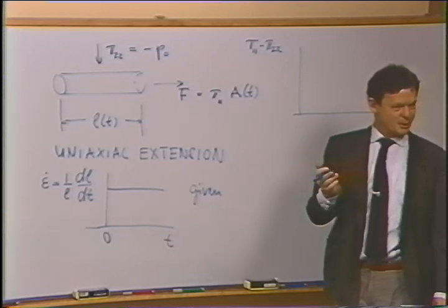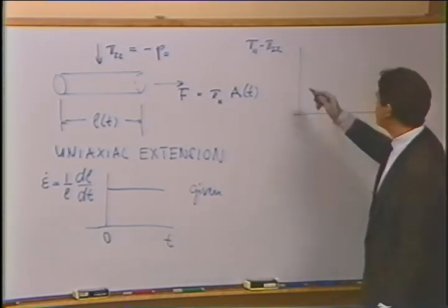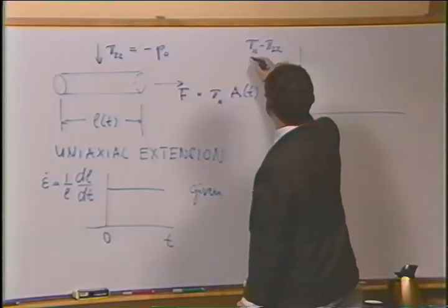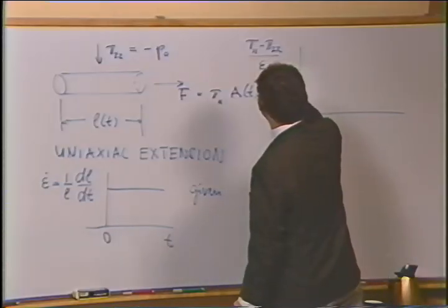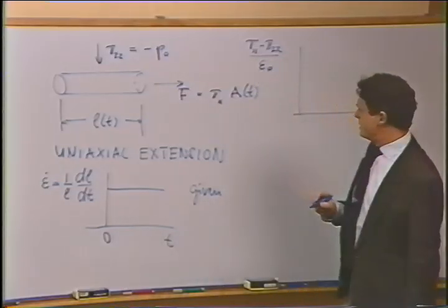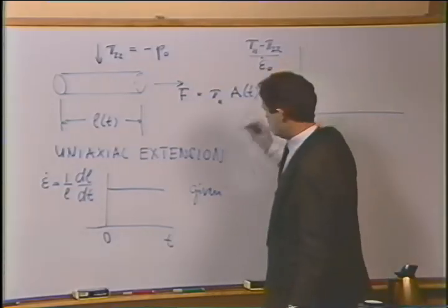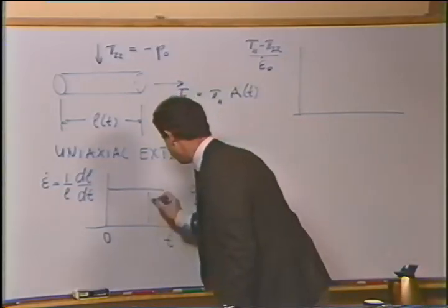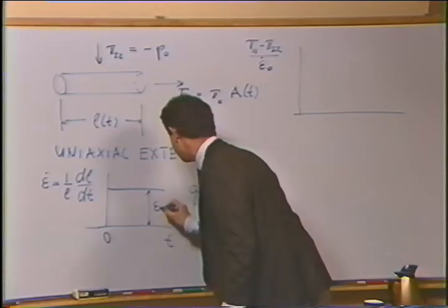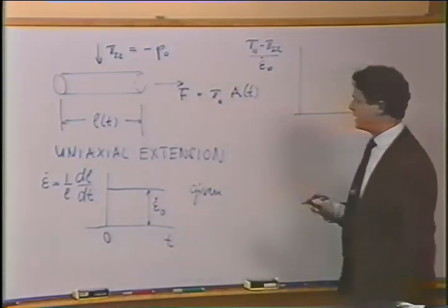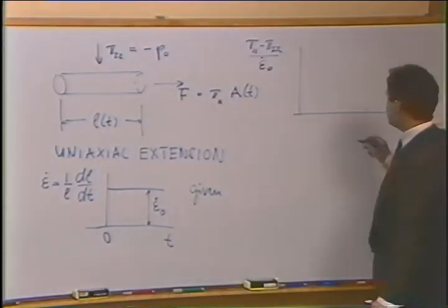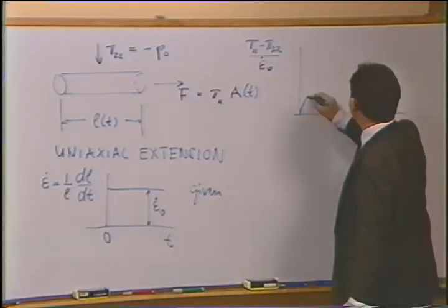Those two stress components are equal. So this is the only material function to look at. Let's divide this already by the rate of extension, which we would say is constant. Here, this is our constant rate which we use for that experiment. Now, data look something like this.